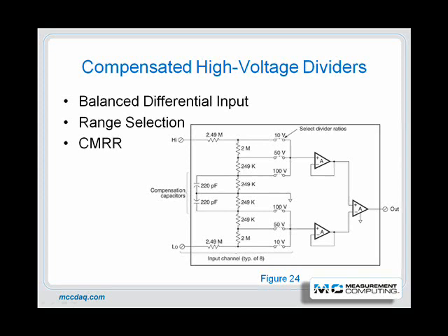One way around the problem is to shunt the data acquisition input terminals, or the divider network, with a compensating capacitor. For example, oscilloscope probes contain a variable capacitor precisely for this purpose. The probe capacitor is adjusted to match the oscilloscope's input impedance and, as a result, faithfully pass the leading edge of the oscilloscope's built-in 1000 Hz square wave generator without undershoot or overshoot.